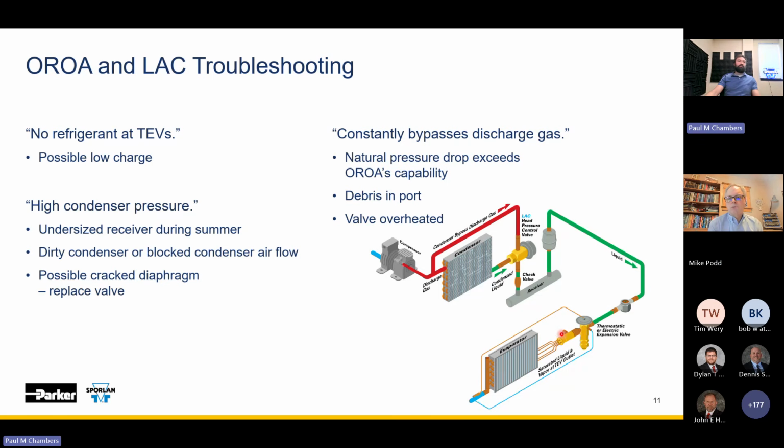What makes you say that? Well, it would be that we're not getting the mass flow. So often if you don't have enough refrigerant in the system, most refrigeration systems operate on a pump down control. And if you energize a solenoid to allow refrigerant to flow into the evaporator, well, if there's not enough pressure drop, you can energize that solenoid and, think about it, sometimes your ambient conditions are colder than your evaporator.